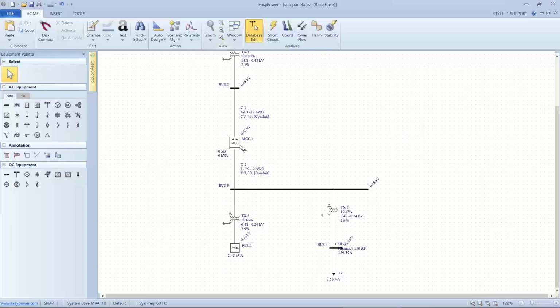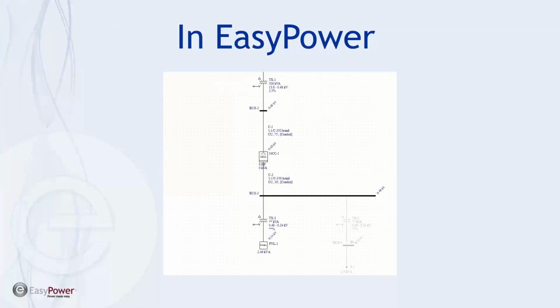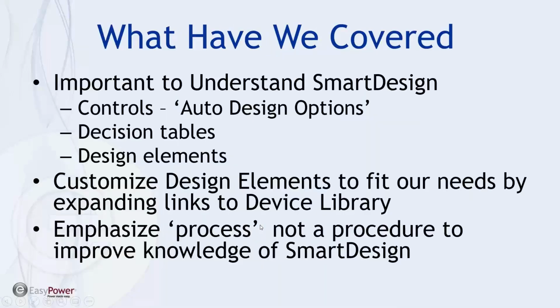Okay, so we solved this a little bit in a roundabout way, but the bottom line is when we're looking at the one-line diagram, it's not a bad idea to simplify the analysis until we understand what the tools are looking at, and make sure we have control over the options. In this case, we were looking at the bus and not the load. We didn't have the checkbox to size everything, so that was a confusing factor.